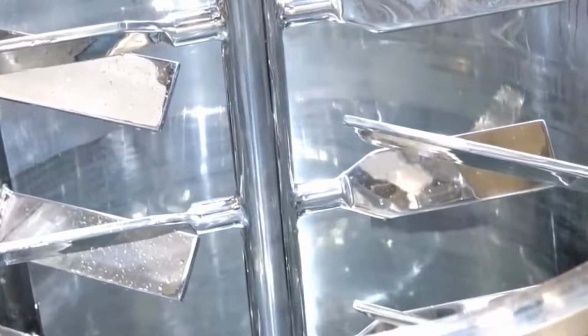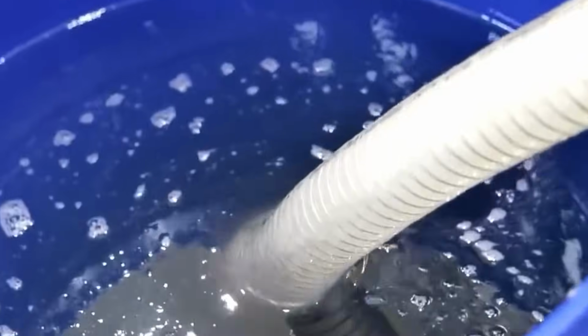Quality parameters are verified at this stage. Viscosity is measured using rotational viscometers, density is checked using digital densitometers, and pH is reconfirmed. Adjustments can still be made by adding small amounts of water, thickener, or pH modifier if required.